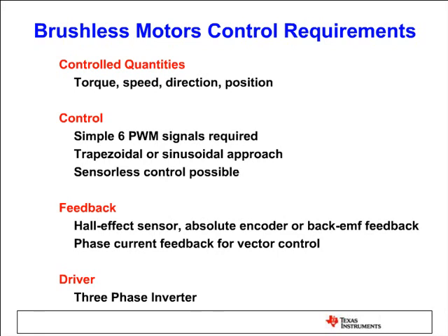Since the motor is designed for trapezoidal application, BLDC motors are mostly effective when we run them with trapezoidal control, not sinusoidal control. But again, today we hear a lot of positive feedback about sinusoidal control of BLDC motors as well, because we don't have phase commutation when we apply sinusoidal control, and it's less noisy, with less EMI and less torque ripple. So I know some customers looking for sinusoidal control of BLDC type of motors.